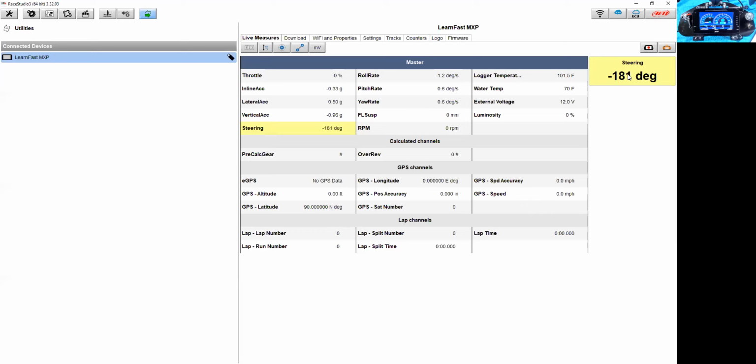I do, and again, it comes back to these data systems being very definable to what you want them to do. Most of our users are trying to do driver performance things, and they're trying to help themselves understand what they've done with their steering wheel and what the reaction of the car was. So steering wheel angle is really the right thing. But if you're working with a team that is developing a new race car, and they really need to know spindle angle, of each the left and the right, then you set it up that way. That's more important to them. So keep in mind, as everything we're doing here, think about what information you want at the end of this process in your data, and that's how you set it up.